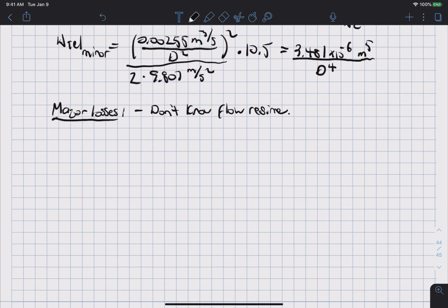So you need to assume that the flow is either laminar or turbulent. Let's look at Re_D again, just so we can get a fix on it. Re_D equals 1951 meters over D. If we consider how small that flow rate is, 0.002 cubic meters per second, it is unlikely that the diameter of the pipe is going to be on the order of a half meter. It's probably going to be much smaller than that, on the order of maybe a few centimeters.